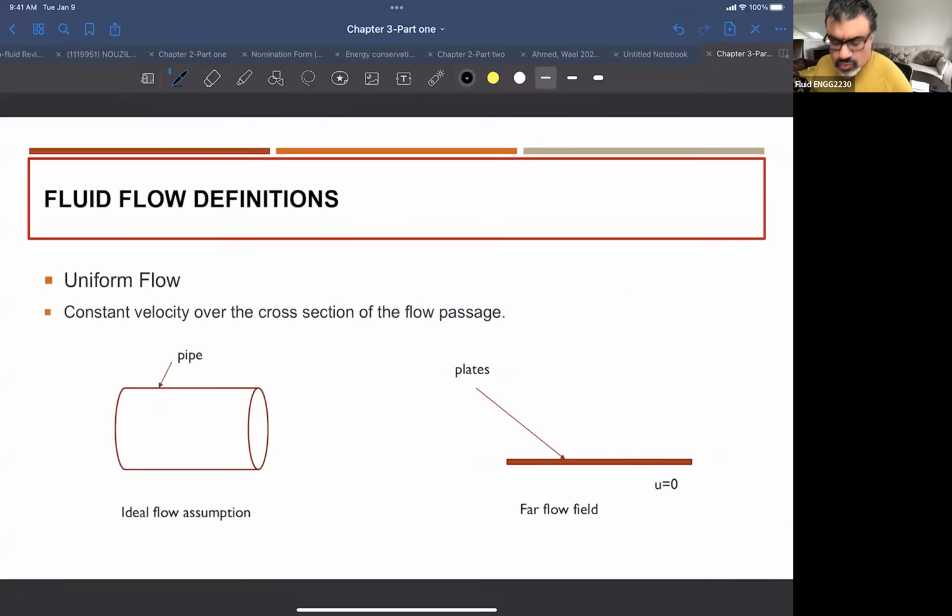So there is another important definition we have to keep in mind. Wouldn't the velocity profile be linear? No, I think we spent a lot of time discussing this. For Newtonian fluids, the relation between shear stress and shear strain is linear, which means shear stress tau is proportional to du by dy. We remove the proportional sign and put an equal sign with a constant. We call it the viscosity.